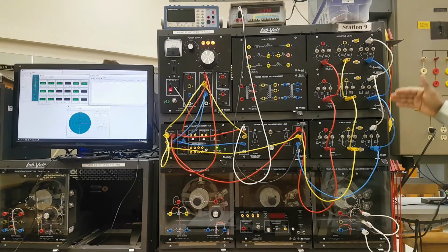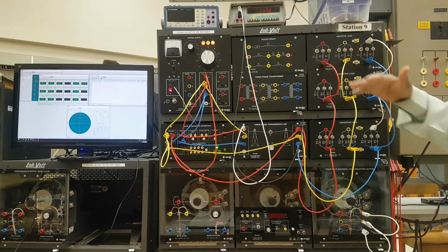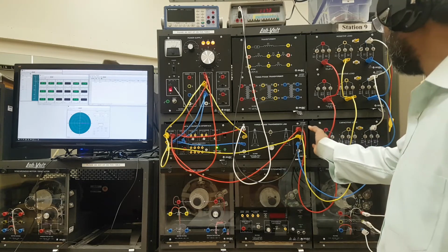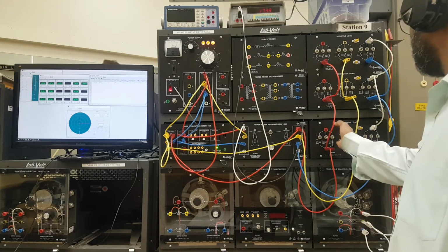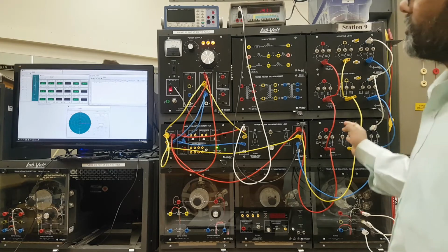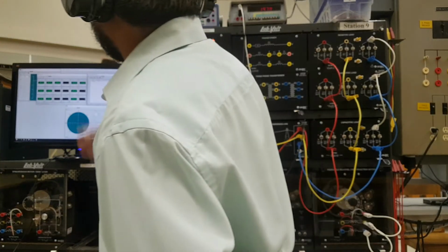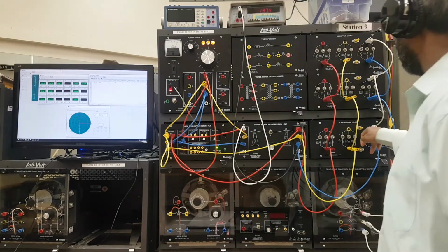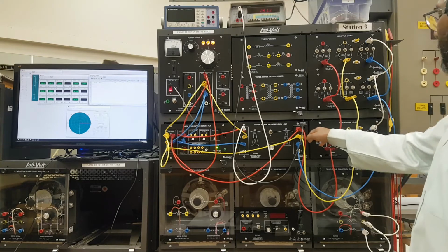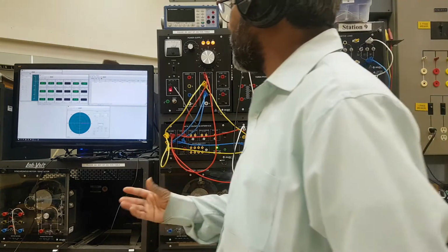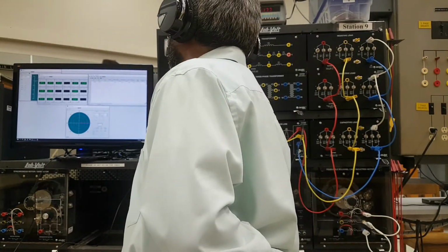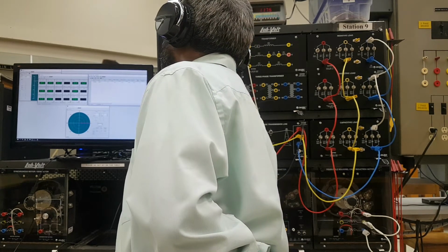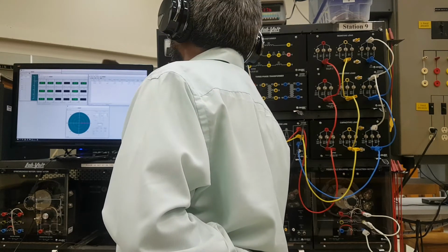Now we are adding capacitance to see if it matches the voltage. If we add the lowest value, 2.2 microfarads in each phase, is it improving? The voltage became 228. It's very high, the difference is very high. That means the lowest capacitance we are adding is not improving. So there is no voltage increment. We'll just record this value.